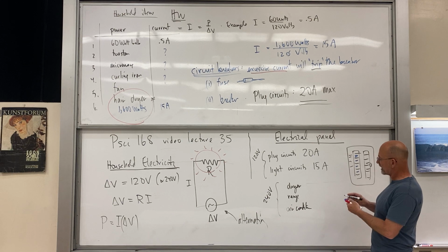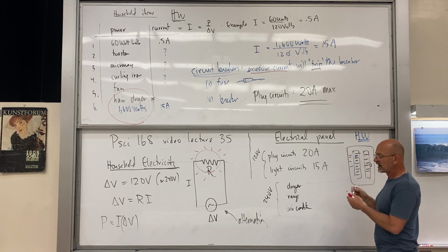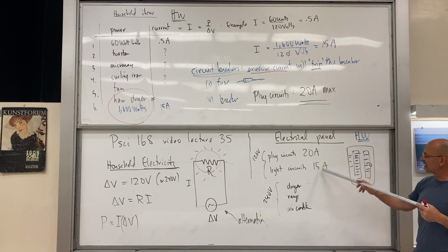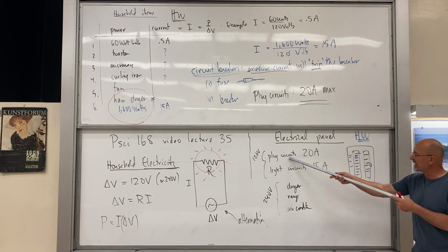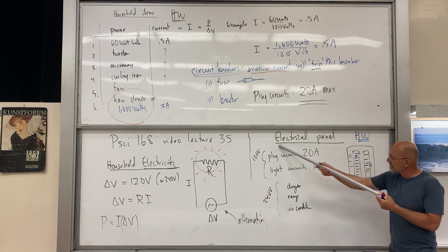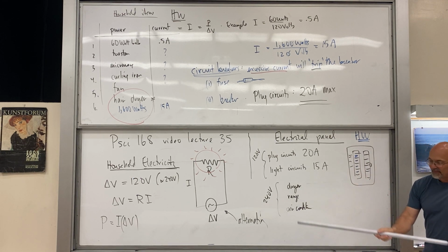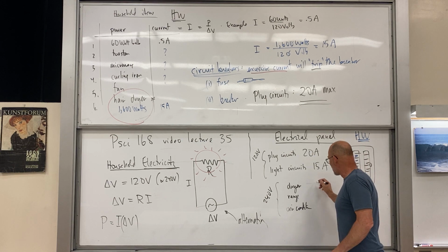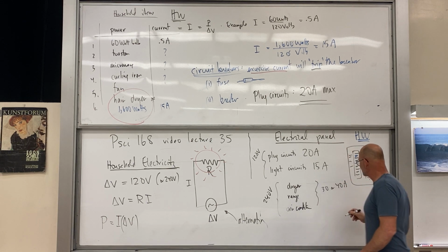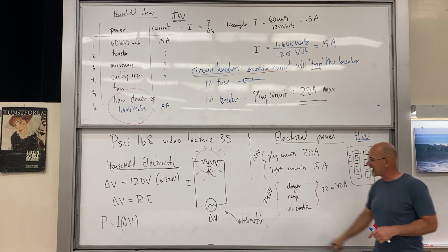So what I'm going to have here for homework as well is hunt these down in your house and see what's going on. Take a picture, make a little sketch, list what you have there. Depending on your house, you'll have different options, but see if your plug circuits are 20 amperes and the breaker will be labeled with 20 or 15. These here are often 30 or 40 ampere, but remember they're 30 or 40 times twice the voltage, so they have quite a bit more power.